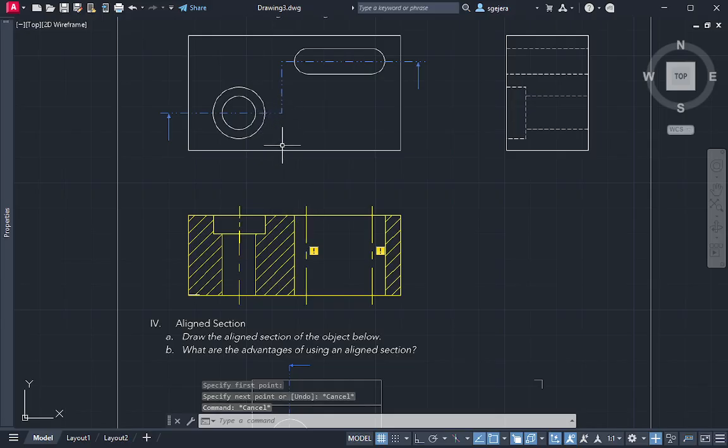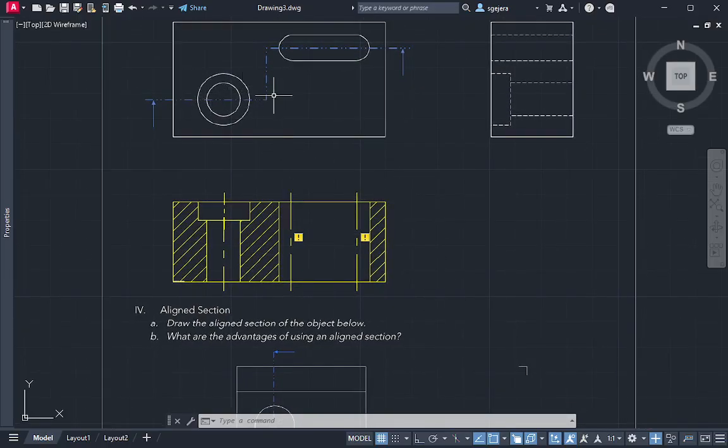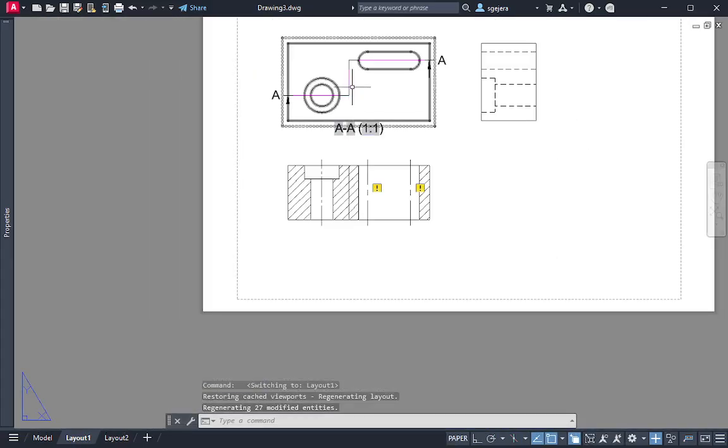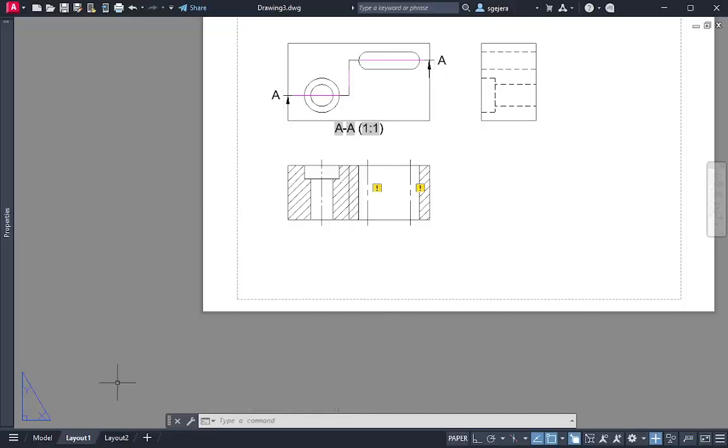Tama naman. Okay? So, parang ganyan, no? Regardless kung nasaan yung parang bend dun sa offset natin, hindi dapat siya lumalabas. For ES1, hindi siya lumalabas. So, wala yung line in the middle, no? Okay? So, if you're doing 2D methods, no need to show the line. But if you're doing 3D methods, automatic kasi lumalabas kung saan nyo ginawa yung parang offset, yung change in level. Okay?